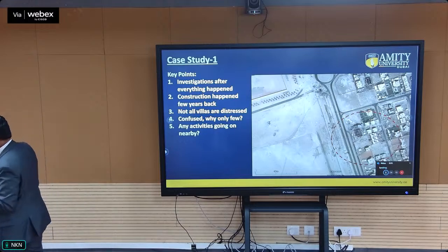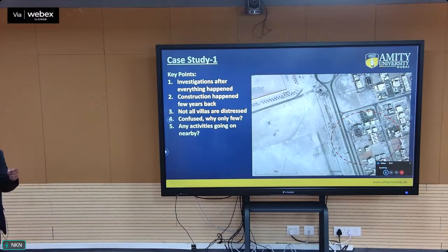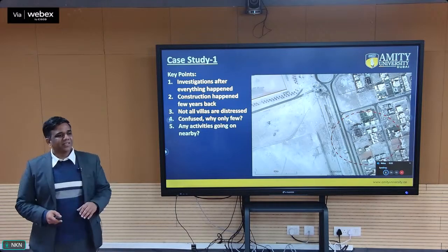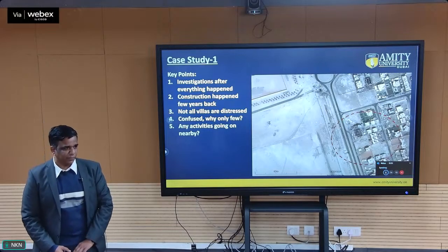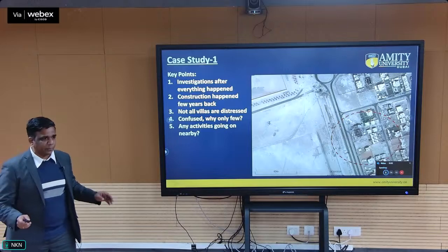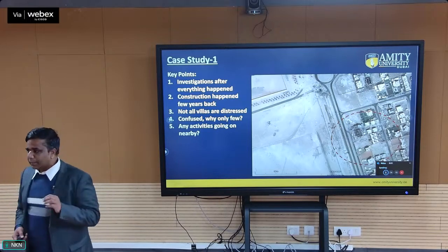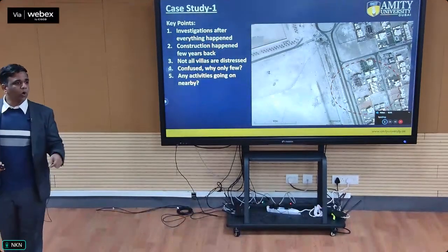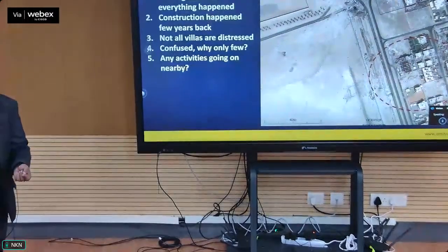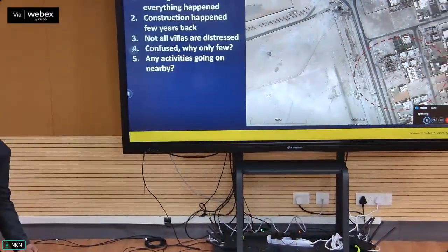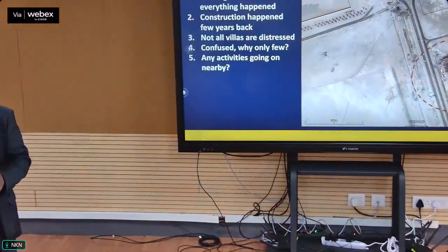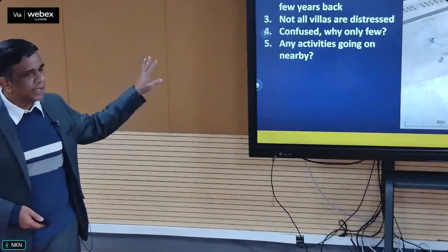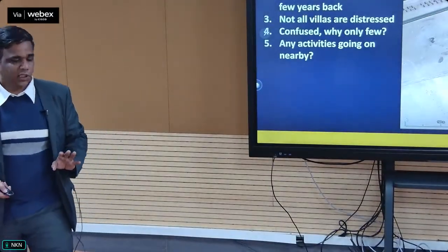So basically, whenever a contractor is given a dewatering job to lower the water table, if you want to lower it to 2 or 2.5 meters, they will keep the water table 3 or 3.5 meters below, so that we have a dry environment when the person is standing inside and working. But if the contractor spends a lot of money making the project safe and dewaters more than what is required, that is also a disaster. The contractor gives us a lot of bills, we pay it, and finally we end up in a disaster. So that is the reason.